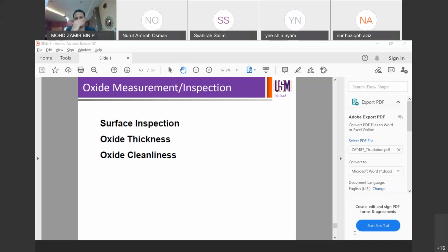Say your targeted thickness is about 5 nano, so your process spec will outline how much plus minus of the process can be tolerated. For example, maybe you can tolerate 0.3 nano plus minus. So if your oxide thickness is 4.7 to 5.3, the process is fine. If the oxide thickness measured is 5.4, it's gonna fail the spec.